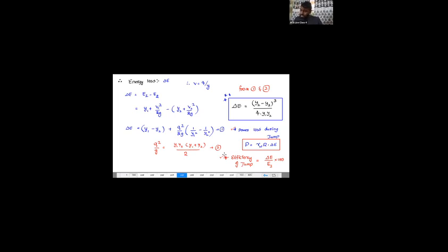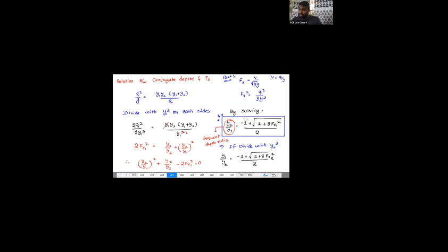Now, based upon the equation of solving here, if you observe clearly, y2 by y1. If y1 changes, then Fr1 also changes. Fr1 means the inlet Froude number. Before the jump, the flow is supercritical, with Froude number greater than 1. After the jump, the flow is subcritical.